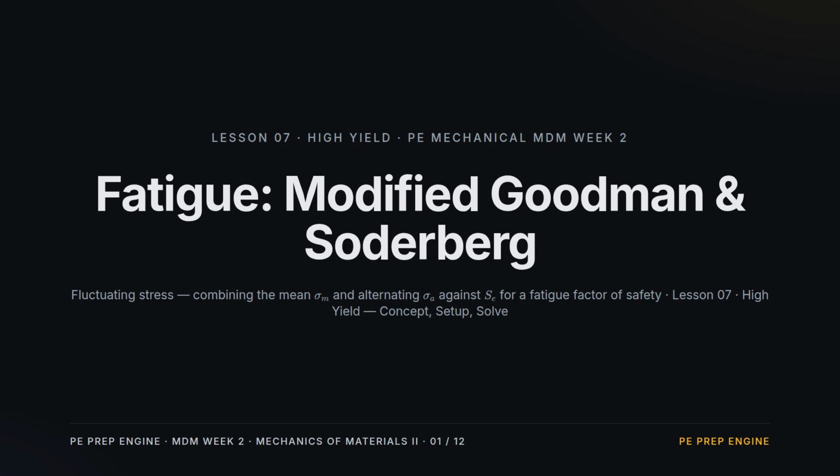Week 2, Lesson 7, Modified Goodman and Soderberg. Last lesson we built the endurance limit, the stress a part survives forever under fully reversed loading. But most real parts never see fully reversed stress. They carry a steady mean stress with an alternating stress riding on top.